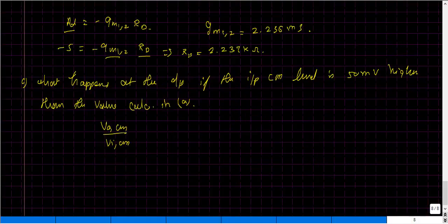So based on that, let us try to compute the value of it and put the things in picture. We know that when we apply a symmetrical input to a linear symmetric circuit, the output will also be symmetric, and we have stated that the nodes having the same potential can be shorted together. It's the same story as what I discussed. I'm just going to add this delta term to represent that small change in the common mode, which is now visualized as a kind of AC component.